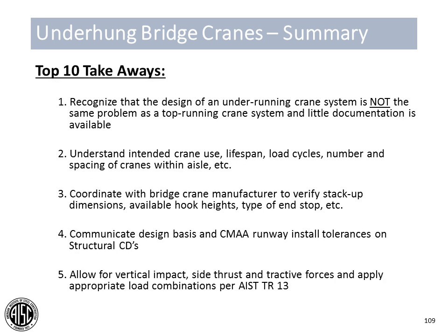So the top 10 takeaways. We need to recognize that the design of these underhung crane systems is not the same as a top-running crane system. We have very little documentation that tells us exactly what we need to do, but a whole bunch of little pieces and parts that we can put together. You need to understand the intended crane use, lifespan, load cycles for the system with which you are designing.